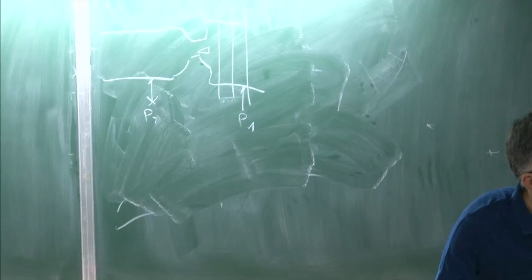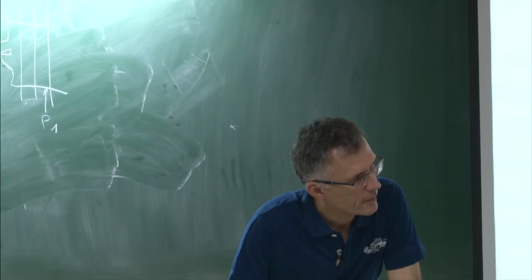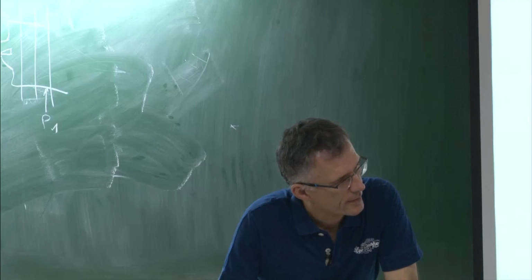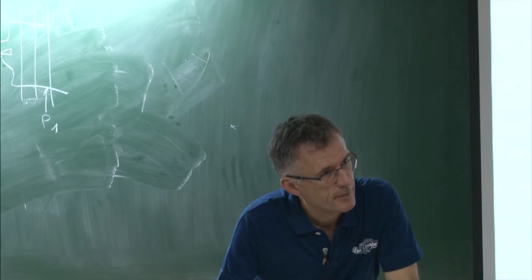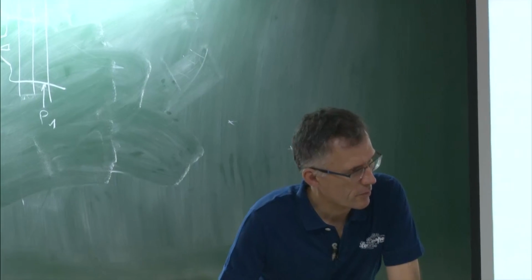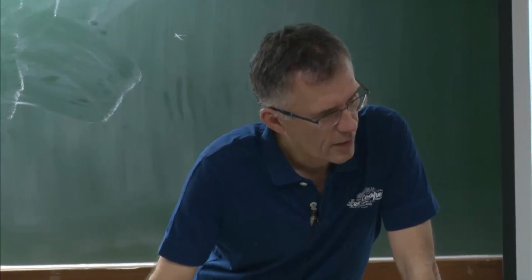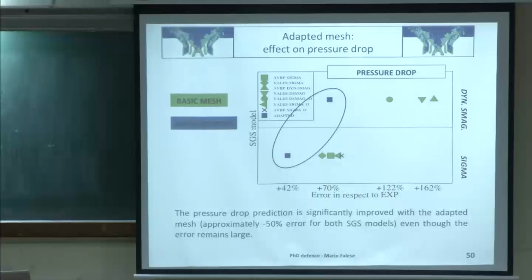So the pressure loss that you're not seeing in LES but they're getting in RANS, is it only because of mesh, or are the LES models near the wall not as good as the correlations we have for RANS? That's the second point. The correlations for RANS have been tuned over years, and they're doing better in the passages here.